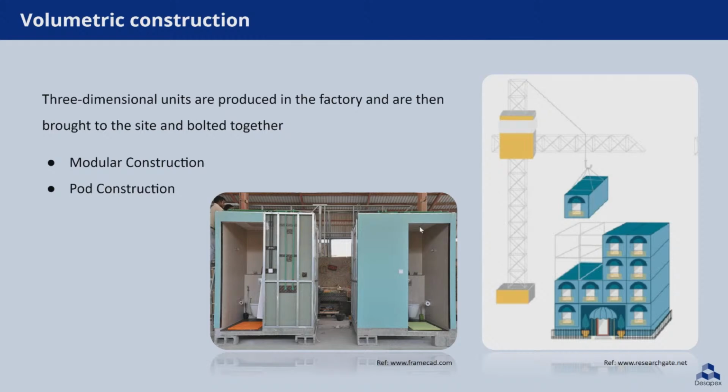These are ready-made rooms that can be connected to form a whole premise. They are held together by a lightweight steel structure. All of the final building services are pre-installed off site, leaving only the final connections. As examples, hotel bathrooms, accommodation blocks, and kitchen unit construction all come under the pod type of construction.